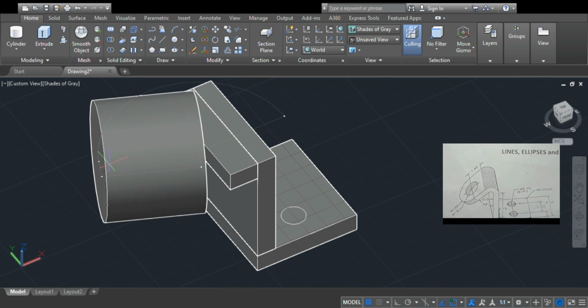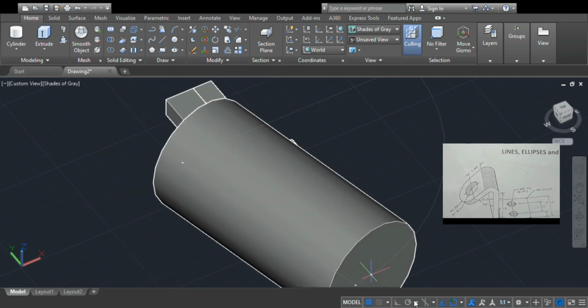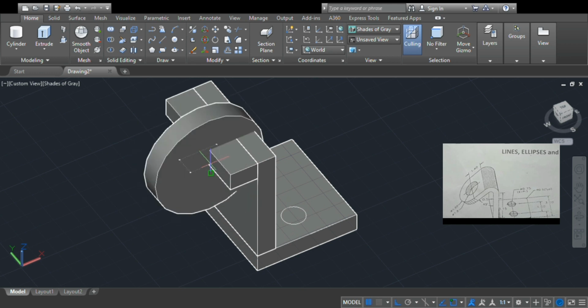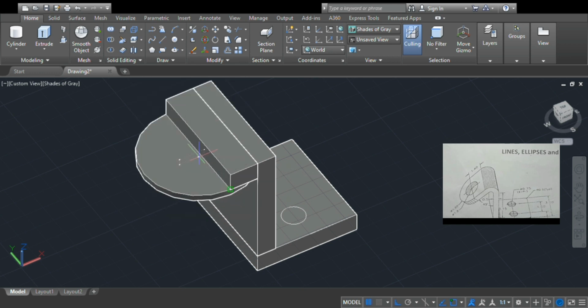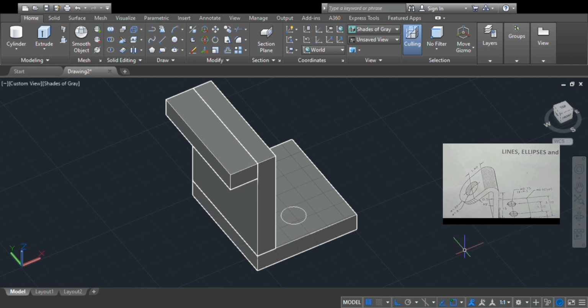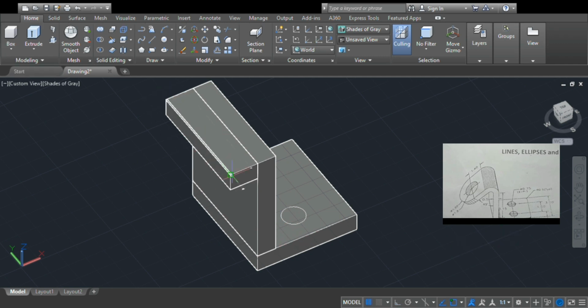After clicking the cylinder and clicking the edge point, you tell the object that it's a 2-point cylinder. And now you can also click this object that tells you what part you want to rotate it to. So you want to rotate it to what point? Click the cylinder again, click the point.